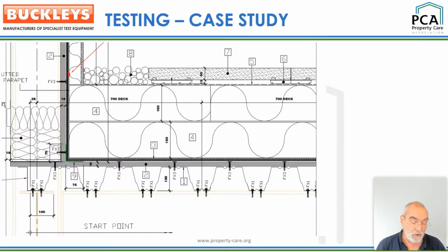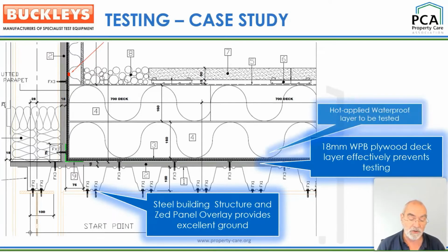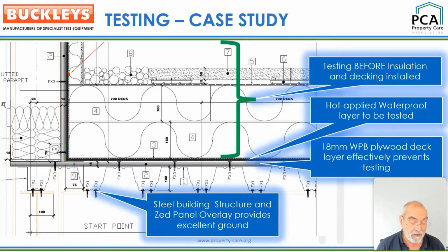Okay, I'd like to look at a case study that came across my desk recently. A customer who carries out independent inspection was requested to report on the following structure and asked our advice. He'd been provided with the roof cross-section that you can see here and wanted to know what we thought. The first thing that stands out is that there's 320 millimetres of insulation topped with a water flow reducing layer, a 15mm slab support layer and 50mm slabs.